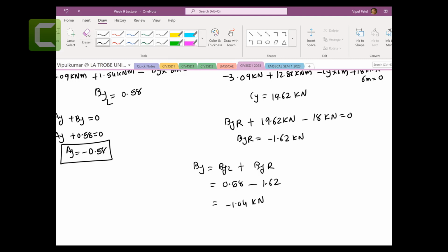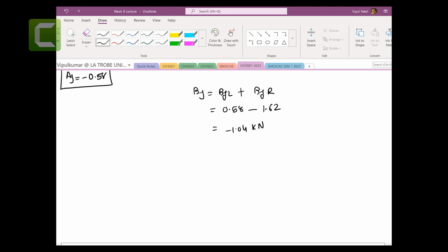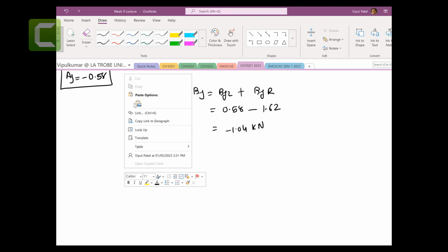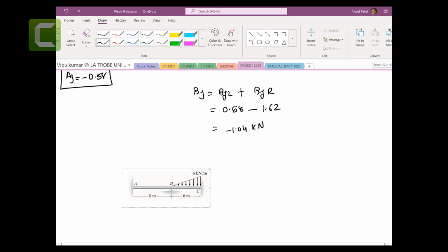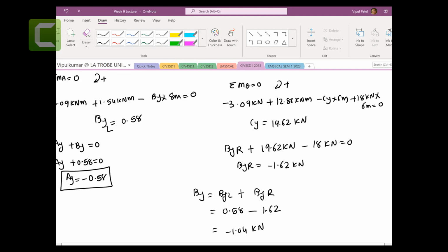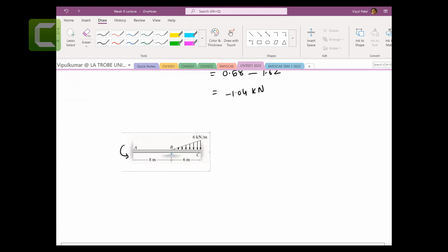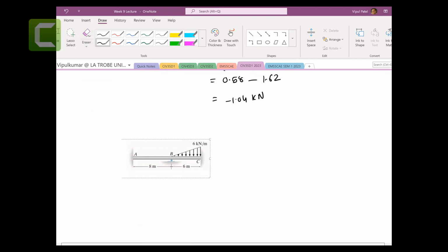So if I put the reaction forces on the figures, copy and paste. So reaction forces, this reaction moment we already got from the moment, 1.54. So going this way, 1.54 kilonewton meters, the reaction moment.